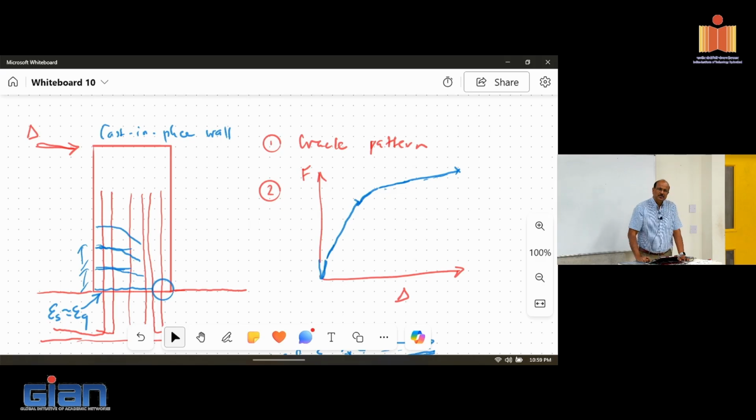What is the steel you mentioned in Europe, doctor? Tempcore, I think. It's the name of the steel. Here we are getting about 20 to 30%. Okay, 50, okay. So the grade 60, what we use in the US, that's 415 here. Right, 450. That tends to have about 50%. If you keep increasing it, then it goes down because they're basically manipulating the carbon content, which affects the behavior.